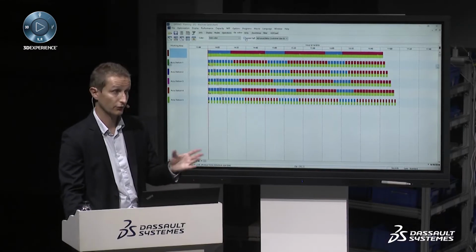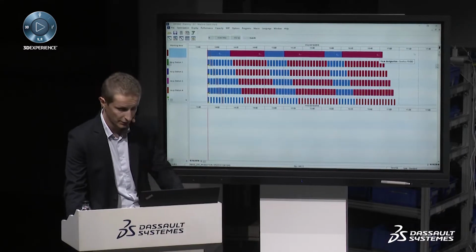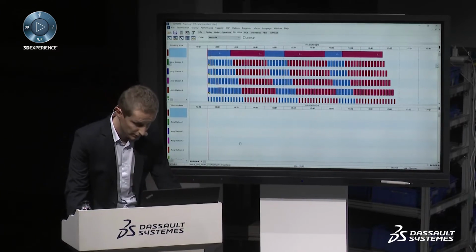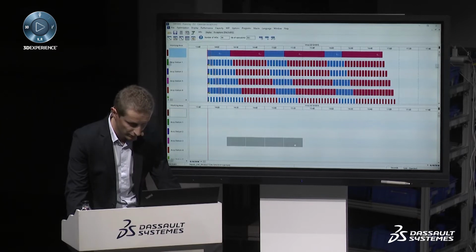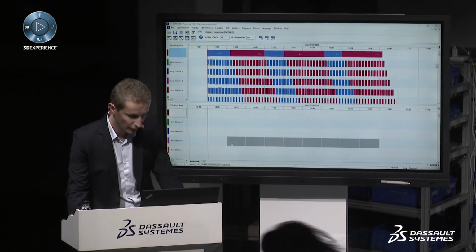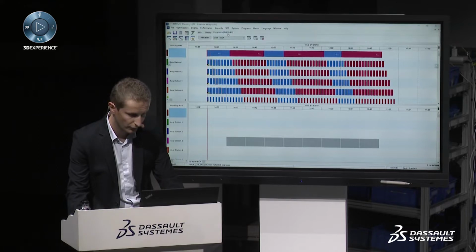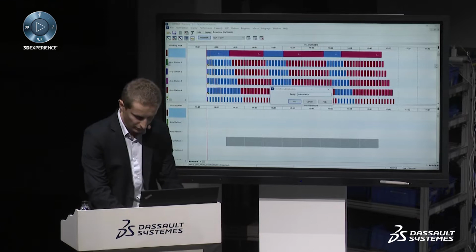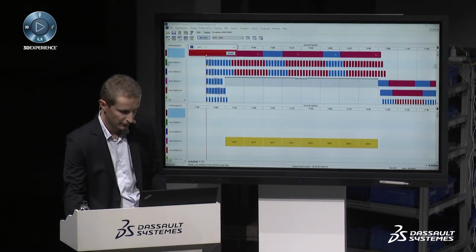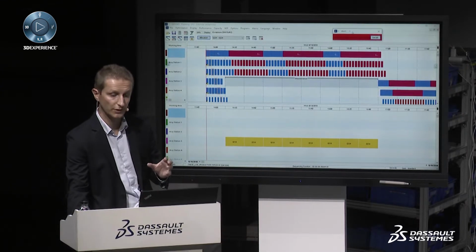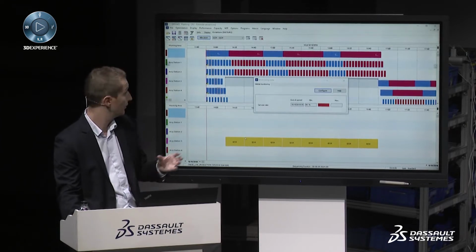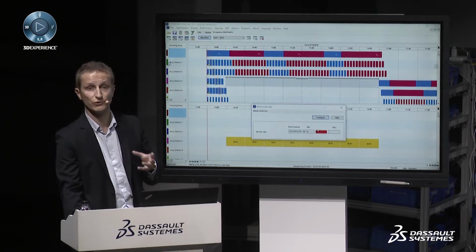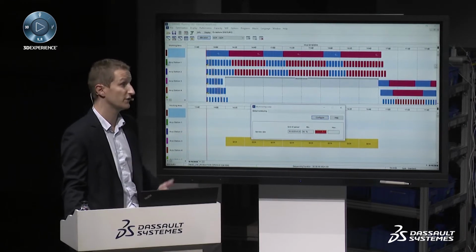Yeah, but we have to plan some maintenance. So good. But let's quickly insert our mandatory and unplanned maintenance on the press. I will just close the station 3 from 2 to 5 for 3 hours. I will put a maintenance designation here and see what is the impact. Okay, so here I have a dynamic and automatic alert warning me that with this new constraint, the maintenance taken into account, the service rate, so the percentage of work orders on time, will drop down to 56%.